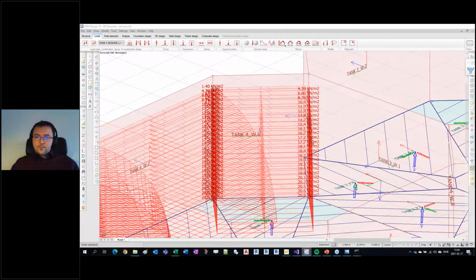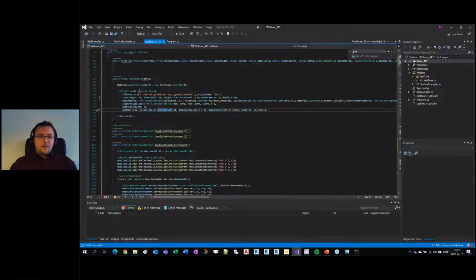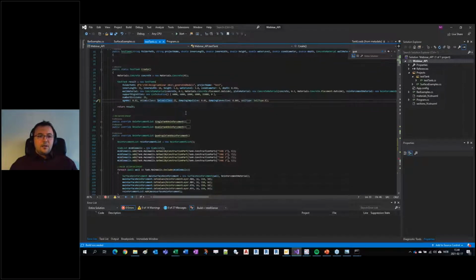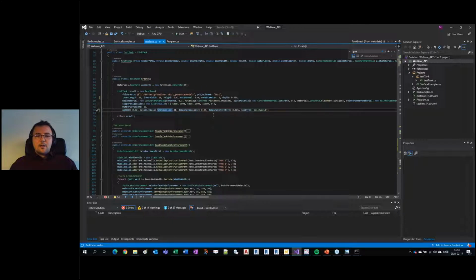So, generating a model from the application also made it easier to divide calculations for ultimate load state and seismic load state, because one has only one file where all the information is contained. All the parameters that are defining a fish tank are contained here, and there's additional information about reinforcement, openings, etc. But geometry is actually defined with only these parameters.